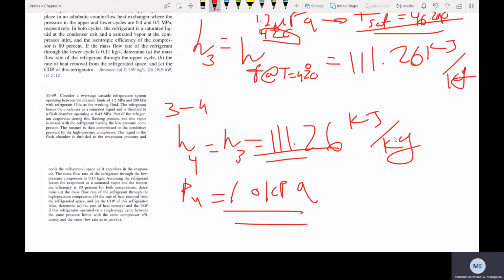So I'm going again, follow me. I'm going to the table that contains the pressure, which is A12. From A12, I go to 60 kilopascals. So for 60 kilopascals, I can see that hg is equal to 278.46.